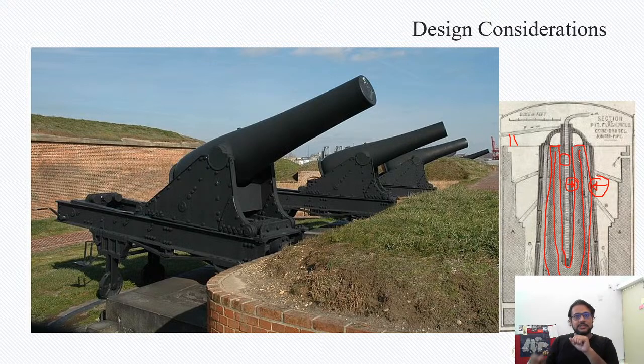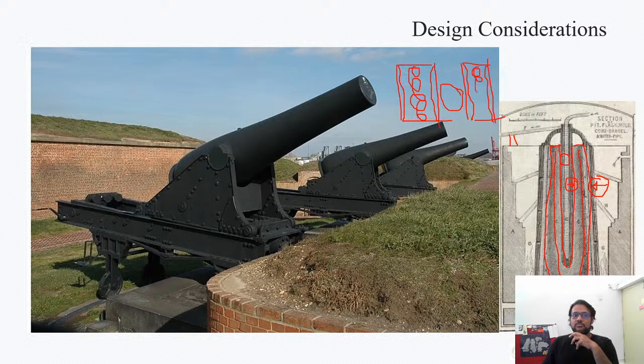Imagine the grain structures at a cross section of this. Let's say this is the cross section of one of the walls, this is the place where the cannonball would lie, and I take a very small sample from here. You would have small grain structures on the edges, probably the same thickness on both sides, and larger grain structures at the center, because the time in which the molten material cooled at this location was much higher. Also, chances are you would have casting cavities and defects along these central portions. Because of this, the cannon would crack like this, because this surface was almost equally as hard as this.